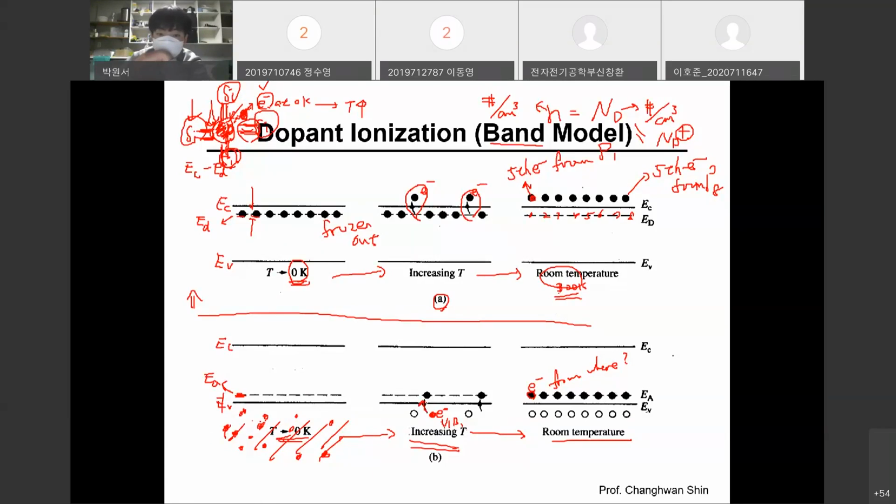But here, interestingly, a single electron now tries to get in this empty energy state. Why? Again, the plus y direction in the energy band diagram indicates the energy of the electron. So if, for some reason, an electron originally participating in a covalent bond between two neighboring silicon atoms has been heated up, then it should take an energy state which has a slightly higher energy level. So originally, this electron has this amount of energy. But now, this electron is excited up, heated up, so that the energy of the electron is this. So a certain amount of energy has been absorbed by this electron.